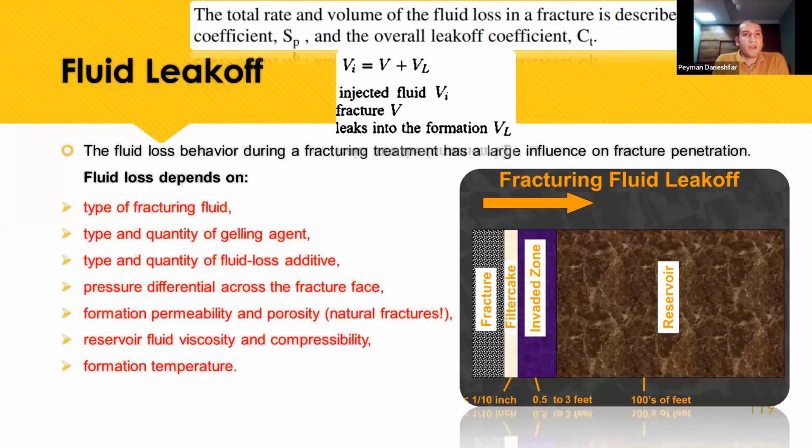To calculate the volume of fluid leak-off, we can consider that our volume of injection will be equal to the sum of the volume of the fracture and the volume of the leak-off into the formation.